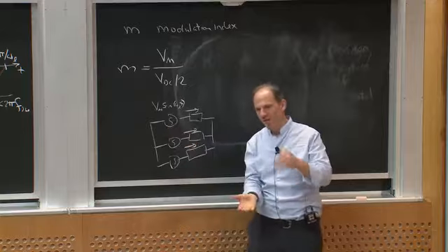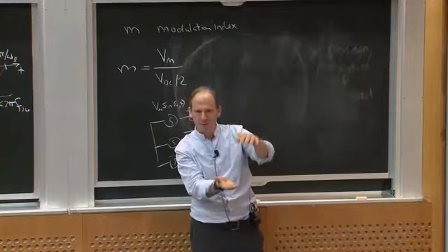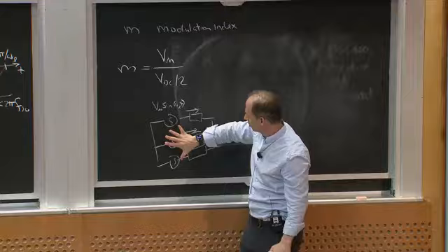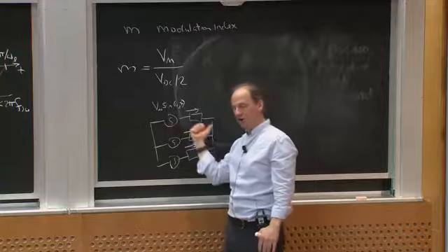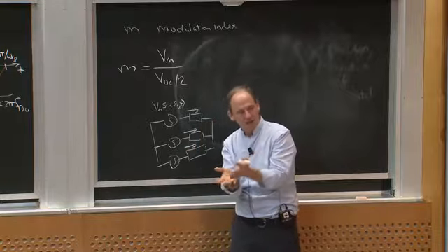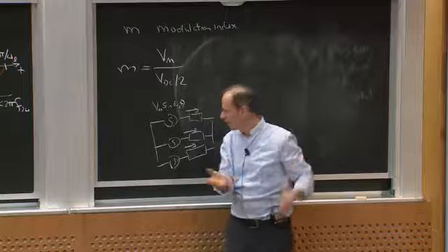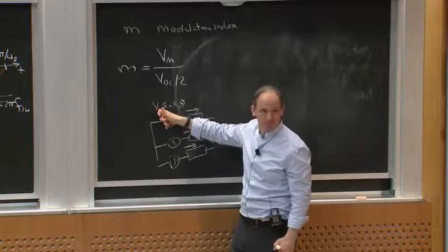So very often, by changing the amplitude of my reference, I change these voltage amplitudes, and then I change how much current I'm driving into my load. So I often want to modulate that. And typically, as I'm going up in speed or going up in power or both, I'm trying to make V sub m bigger. Does that make sense to everybody?